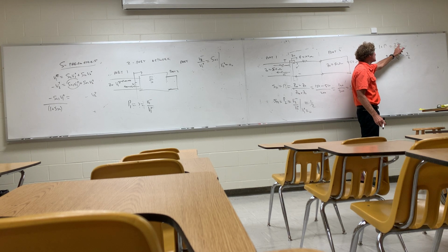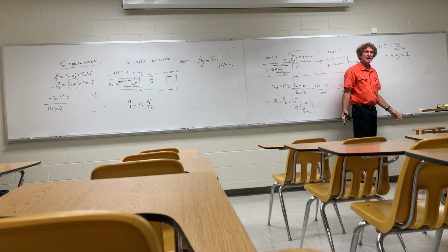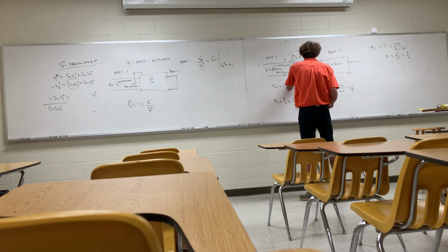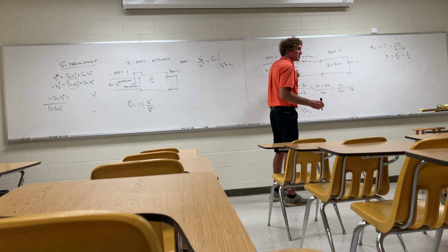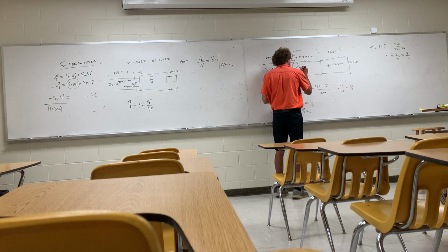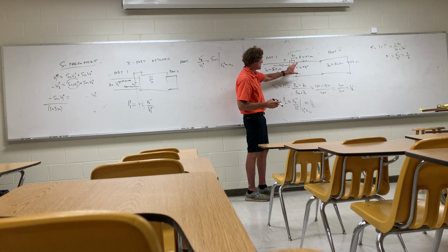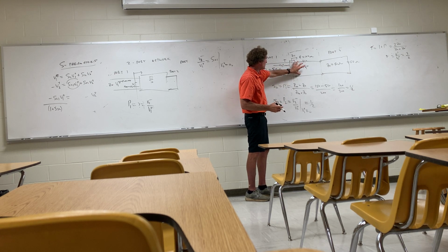We talked about it. So 2 times 150 is 300, right? 300, and then it'd be 150 plus 50 or 200, 3/2. It works out either way. Do y'all follow? Okay, so now I can say that right here, when I look at that voltage, this voltage is going to be tau times V1 plus. And that would be the voltage just on the other side of this connection. Some of that wave's going to reflect back, but some of it right there is developed right across there, okay?